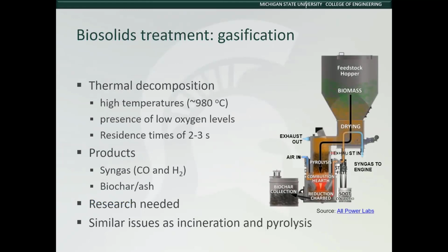Gasification is similar to pyrolysis. However, it's conducted at higher temperatures and in the presence of oxygen. The residence times are slightly less than with pyrolysis. Residence times of 2 to 3 seconds are necessary. The products are syngas and biochar. However, research still needs to be done in order to ensure that there is a fluorine mass balance and to show that cleavage of the carbon-fluorine bond actually occurs.